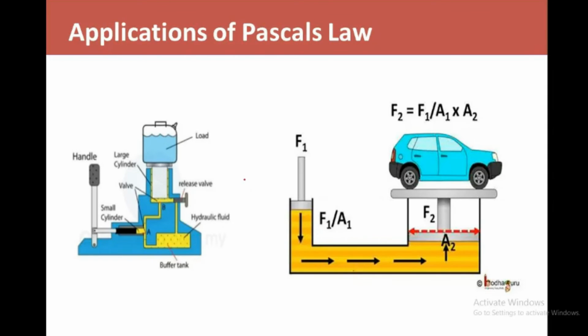अब पास्कल्स लॉ के हिसाब से क्या होता है? We will see. Now consider this case. In this case, there is a small area. So this small area is A1. And on this small area A1, suppose आप अपने फुट पेडल से स्मॉल फोर्स F1 लगाओगे. सो आप कितना प्रेशर जनरेट कर रहे हो? प्रेशर इज F1 एंड एरिया इज ऑल्सो A1. तो यहाँ पे सपोज आपने 1 न्यूटन का फोर्स लगाया और यहाँ पे एरिया 1 मीटर स्क्वायर था. सो आपका प्रेशर कितना हुआ है?